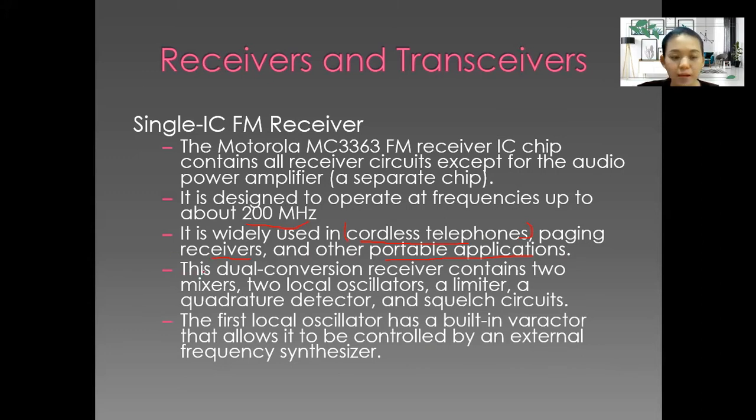Okay, and this dual conversion receiver consists of 2 mixers, 2 local oscillators, a limiter, a quadrature detector, and the squelch circuit. The first local oscillator has built-in varactors that allow it to be controlled by an external frequency synthesizer.